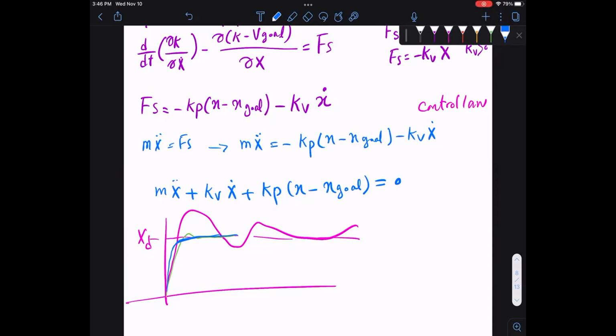We are discussing only one joint right now, right? I will show you what to do when you have multiple joints, but right now we have one joint. So now plot that, see the response; if you like it, good, if not, tune until you get this. How to tune those? There are different ways: algorithms, adaptive methods, you can use the MATLAB tuning toolbox, you can create a system in Simulink, right? So there are different ways of tuning, but you build the dynamic. The dynamic is complete now. So remember, this part is the fake part we added. It didn't exist in our system.